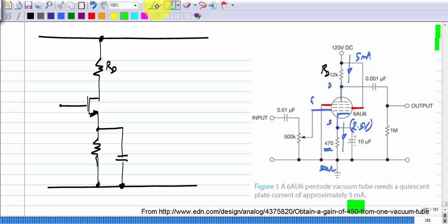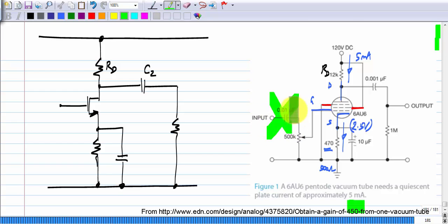This is quite familiar. We have AC coupling to take the output. This is C2, and in this case it is some 1 nanofarad device. And also, when we bias it like this, we would, in case of a MOSFET, bias the gate using a voltage divider. Here you can see this capacitor is relevant only for signals. So in the quiescent condition, the gate of the vacuum tube, or the grid of the vacuum tube, is connected to 0. Now remember,